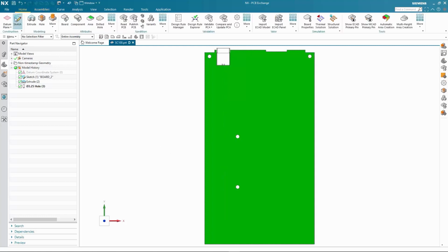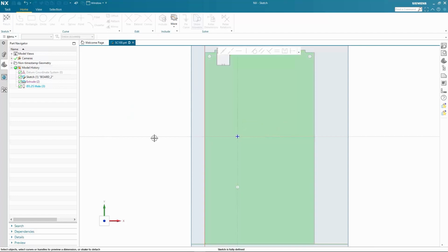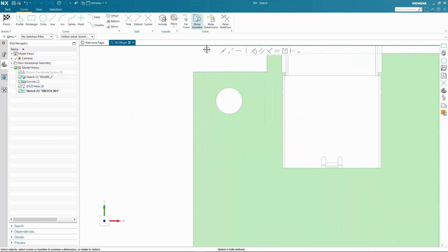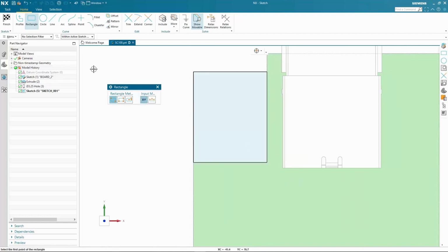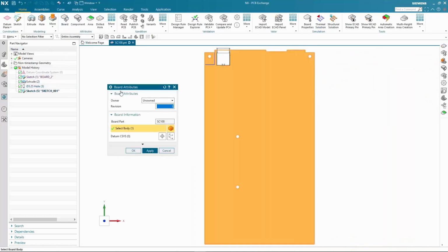The last piece of geometry I want to add to properly pass to the ECAD designer is a placement obstruct. I'll create one in the upper left corner to avoid any hardware engineers from placing components that may interfere with my mechanical assembly.